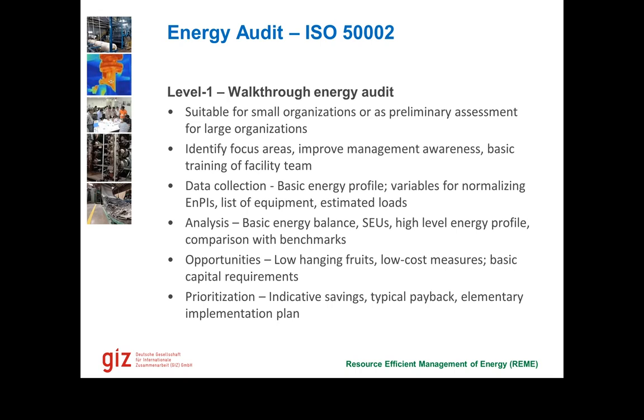Then conducting a very basic energy balance at the energy input level, that is, how much percent of energy we are getting from each of the energy types, and just qualitatively assessing what are the biggest energy users. At this time, we might not have enough data to actually quantify the energy users, but at least we might have a very high level of energy profile rather than having a very detailed one. And as everybody has been saying earlier, low hanging fruits, low cost measures, basic capital requirements, these are the opportunities that we identify here, and where we can start building trust in the company.